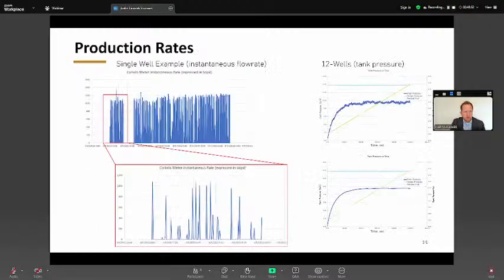And looking at this, if you leveled it out, you can actually create a steady state model based upon this flow rate if you properly pick your production levels, such that you can actually see for 12 wells coming into this facility, that's that top right chart, that's the real pressure curve, and the bottom is a steady state curve. So just because we're seeing this really erratic behavior, you can represent it in a manner that's steady state and matches reality. Coming back to the field validation.